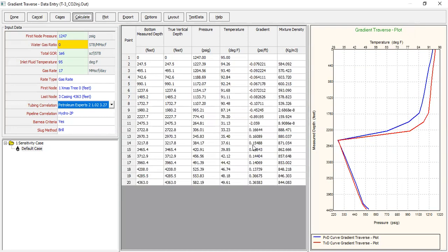I can say that in this condition, with the given wellhead injection pressure, the targeted gas rate, and the given fluid temperature, 95 degrees Fahrenheit, I cannot be sure that I can achieve dense phase CO2 along my wellbore when I'm injecting my CO2. Okay, so I will take a picture of it, and